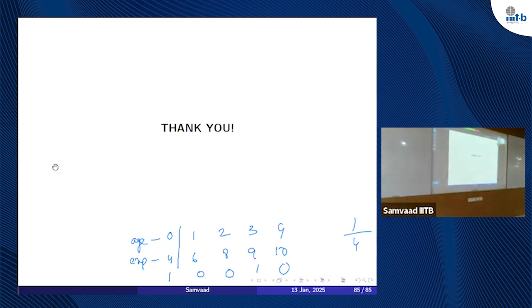Latency. You have the critical path, right? After you do the implementation on FPGA, you will get a maximum frequency. From there, I go back to the simulation. After implementation, you can check the simulation. When training, I have a one output signal, training done. Starting from the reset till training done, I'm counting the clock cycles, and multiplying with the time period, I get my latency. Understood?